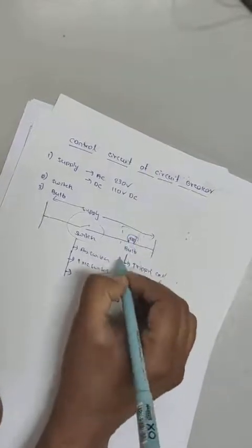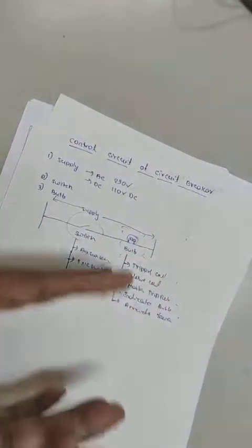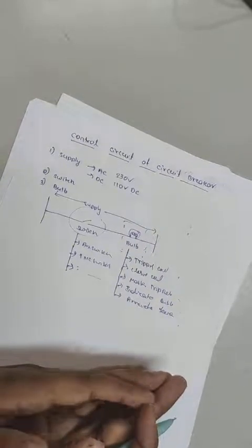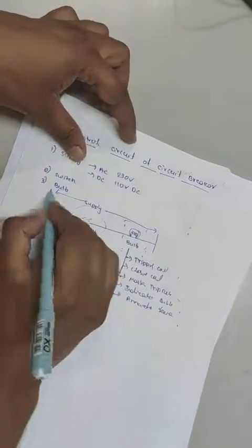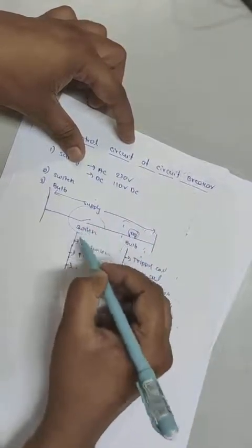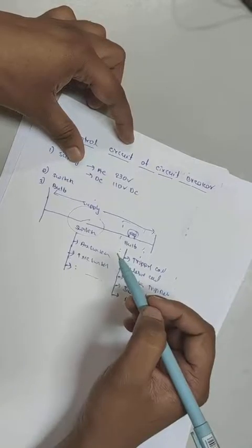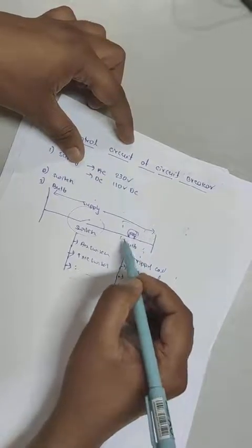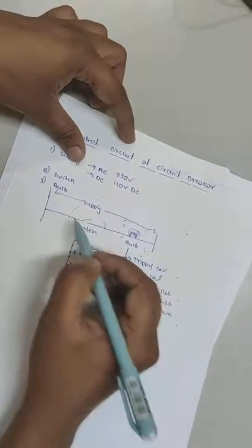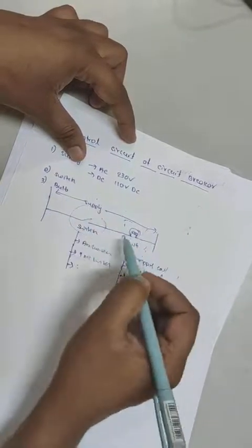The positioning of these three components may be situated in different parts of the electrical system. Likewise, for an annunciator fascia in the remote annunciation desk, the supply will be fed from the annunciator fascia itself, the switch will be in the breaker, and the bulb will be in the annunciator fascia itself. Like that, the positioning of these three elements varies.